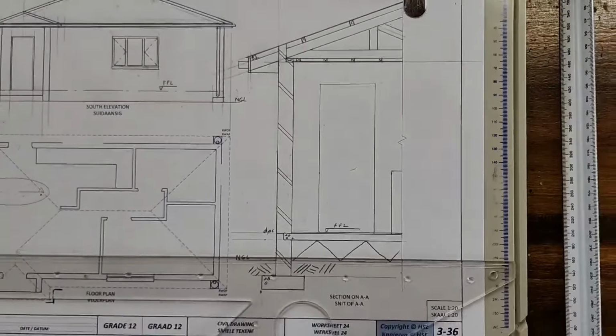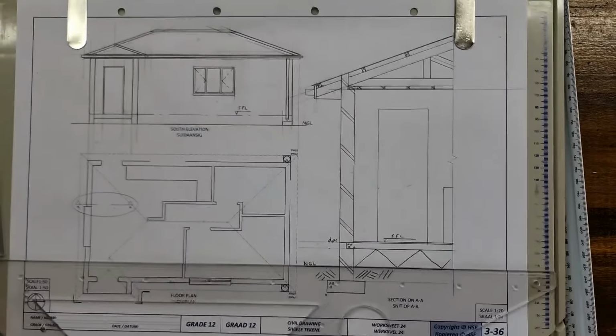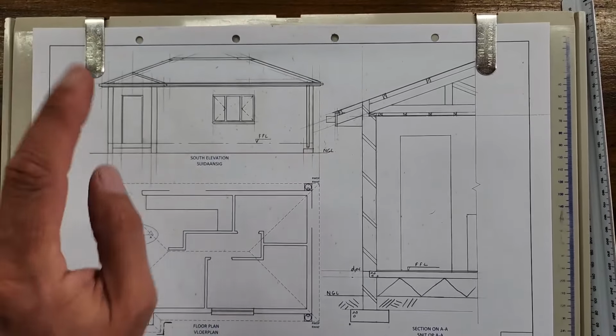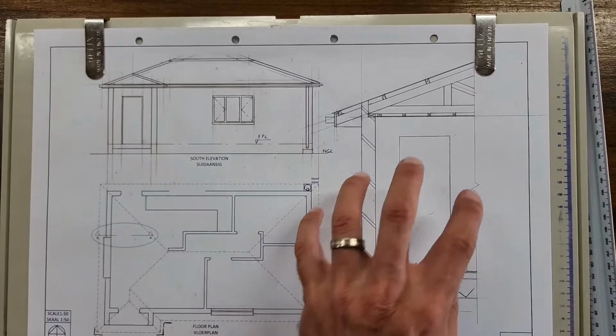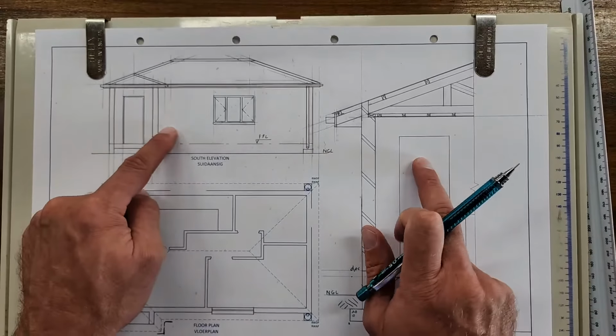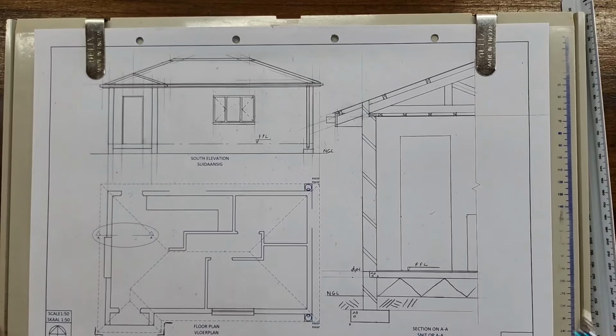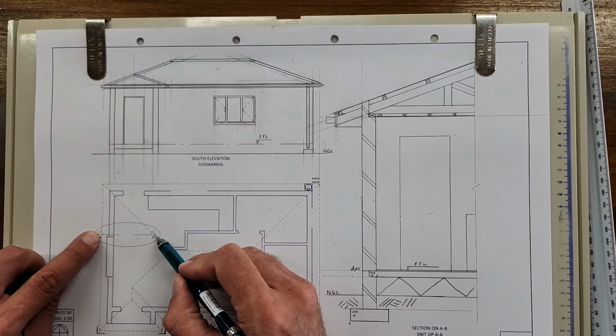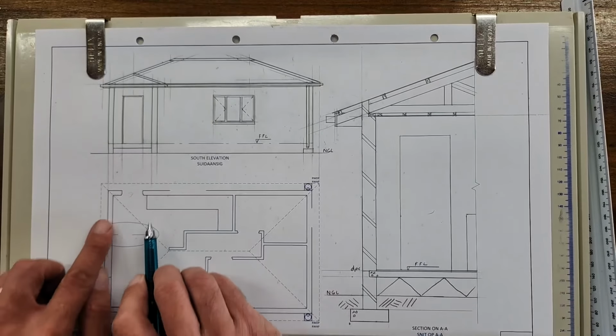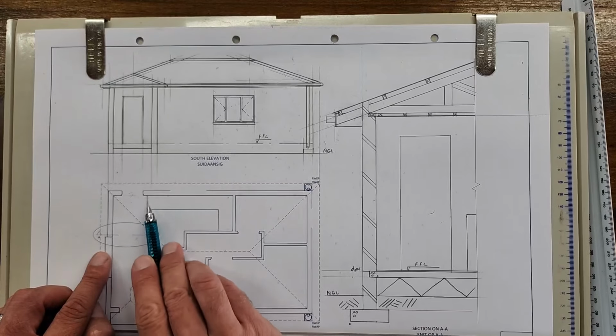Alright, let's zoom out and let's just look at what is drawn here. Alright, so in this session we've looked at the elevation and the sectional elevation, which is two key components. The floor plan, I'm sure you should absolutely nail it. Make sure that when you look at your cutting plane, in the direction of the arrows, what do I see? I see that door, I see this end.